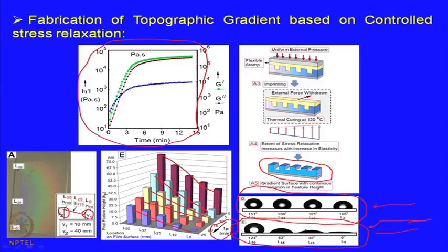Firstly, you fabricate a chemical wettability gradient, and then you attach particles to it in progressively varying numbers. Or of course, one can prepare custom tailored stamps or masters with progressively varying feature size. But while discussing soft lithography, we have repeatedly talked that special stamps anyway have to be fabricated by some high-end photolithography or other type of lithography techniques, and therefore they are expensive to implement.